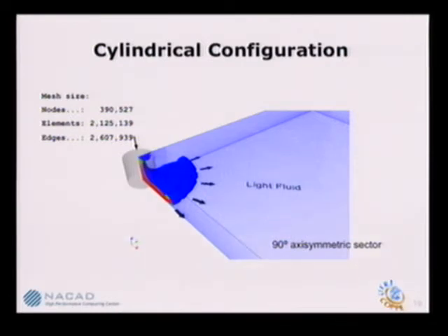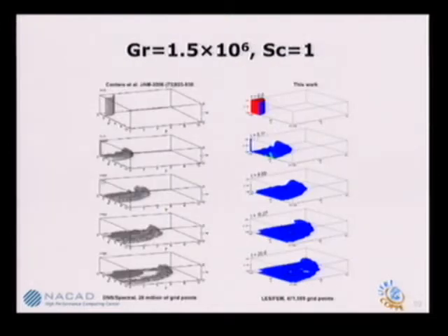Okay? And we're going to see this, but due to our lower resolution in our large eddy simulations computation, the number of lobes and clefts we got are smaller than the high resolution, highly resolved DNS computations we are taking as reference. See, a DNS spectrum with 28 million grids, they have much more resolution here. If you count the number of lobes and clefts, this remains constant, and remains constant in our simulation with half a million grid points.